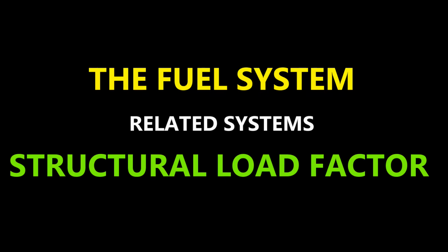Of course, you've got actuators on each wing, and those are powered with your basic 28 volt DC. One's coming from one bus bar, and the other one's coming from the battery bus bar. Okay, your bus bar 2, and then your battery bus bar. So of course you've got backup there if one fails, so that's what's happening there.